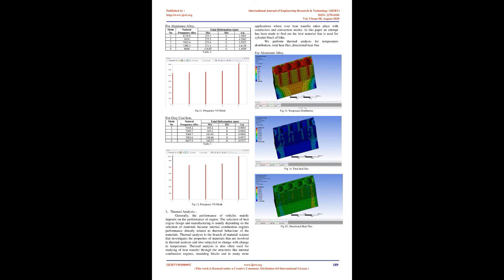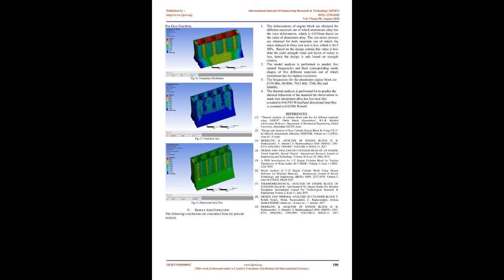The natural frequencies of a component are extracted in order to avoid the resonance condition, which can occur if natural frequencies of components match with the excitation frequencies. Therefore, extracting the natural frequencies of components and keeping them away from excitation frequencies will reduce the chances of resonance condition, where the component will deform at its maximum amplitude.